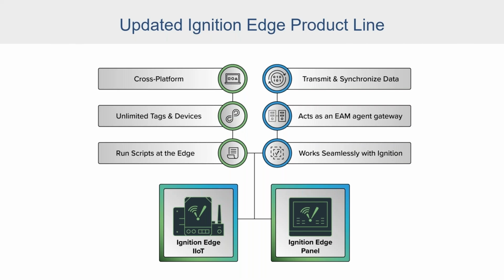And also for people that are collecting data, there was a 7-day limit so that you could only buffer data and then forward that data to a centralized system, and the centralized system is where you would store long-term data. Another change we made is we said this data buffer would be more valuable if it could hold at least a month's worth of data. There's a lot of applications out there that require a month of data. And so now instead of being limited to 7 days, it's limited to 35 days.